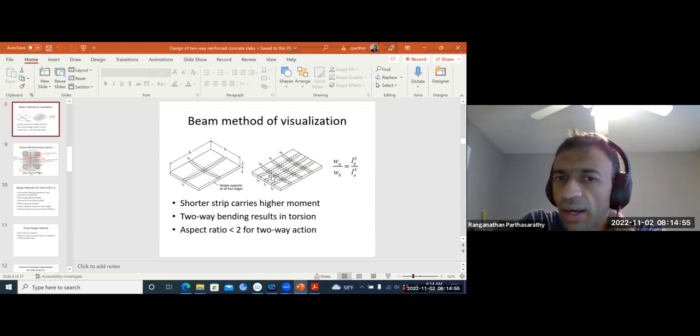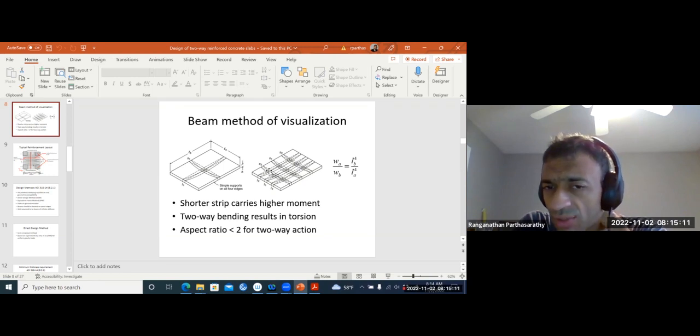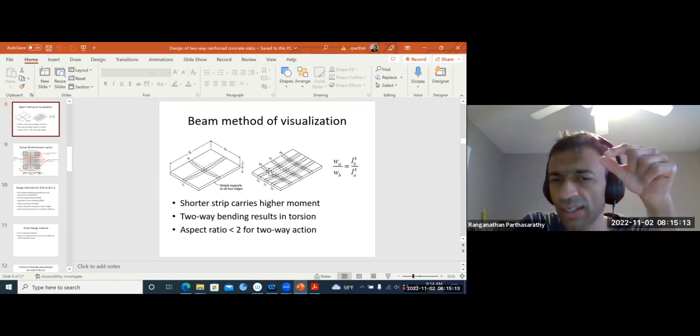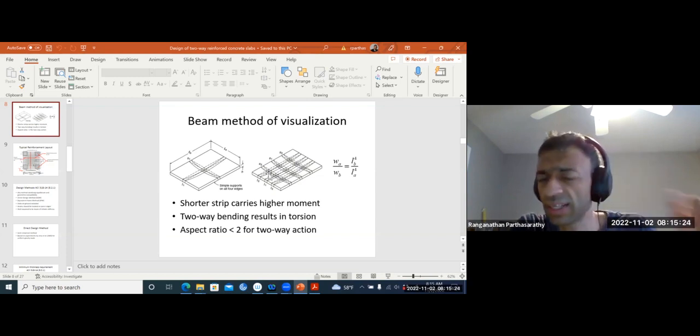Now, when S2 has to bend in this way, then correspondingly, at the intersection point in L2, it has to introduce a twisting, right? For S2 to be able to freely bend like this, it has to twist the section at L2. So did you all get that point?